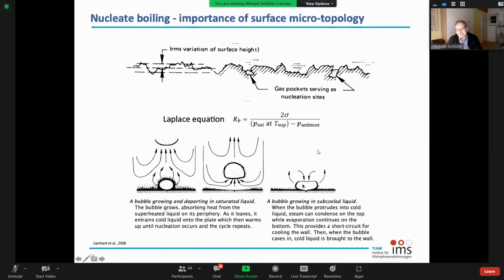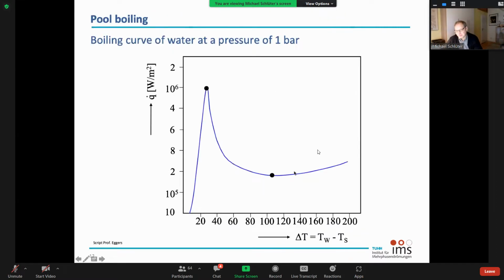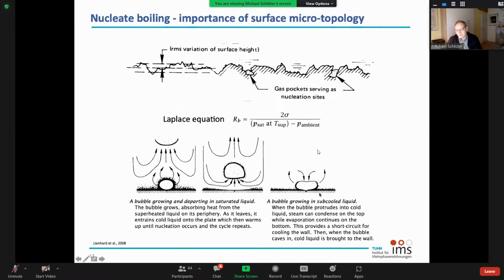At the beginning, if the water is too cold outside, then the vapor bubble will rise up, and due to the cold water above, the bubble will condense again. So you will see that bubbles are appearing at the ground, they are rising upwards, and suddenly they're disappearing again. And sometimes they're disappearing again as well here at the ground, because of direct evaporation and condensation, because the liquid in the surrounding of the bubble is too cold. This is another important and interesting effect.